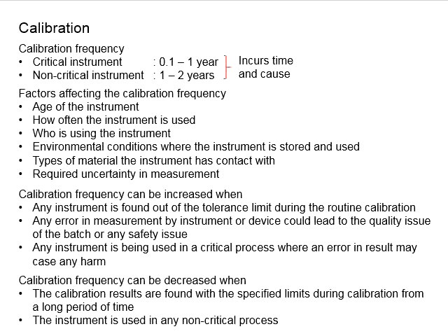For example, after several times of routine calibrations, the equipment seems to be quite accurate. That means most likely the frequency may be reduced. Or every time you do the calibrations, you realize that it's always out of the tolerable limits. That means most likely you will need to reduce the gap between the calibrations.